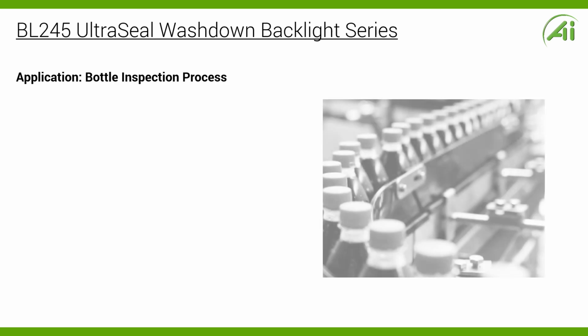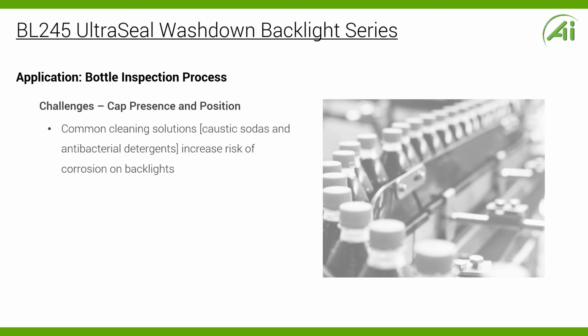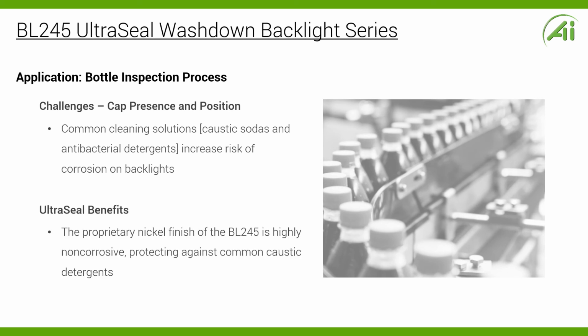Let's take a closer look at some of these challenging applications. First off, we have the bottle inspection process, and specifically here we're involved with the backlight in cap presence and position. Clearly in this case, common cleaning solutions often include caustic sodas and antibacterial detergents. These increase the risk of corrosion considerably on the materials all around as well as the backlights. The benefit here, of course, is the proprietary nickel finish that we offer on this product. It's very non-corrosive and certainly will protect against these caustic solutions.